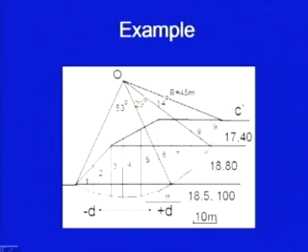These slices are trying to destabilize; if I take the vertical weight and then its component parallel to the sliding surface, the components will be in this direction, here it will be in this direction, here in this direction, and so on until you reach here, where it will be almost horizontal. Now, when you go towards this side, the component tangential to the failure surface is in this direction. So, they are trying to do the opposite. So, we have taken D as positive in this case and D as negative in this case.